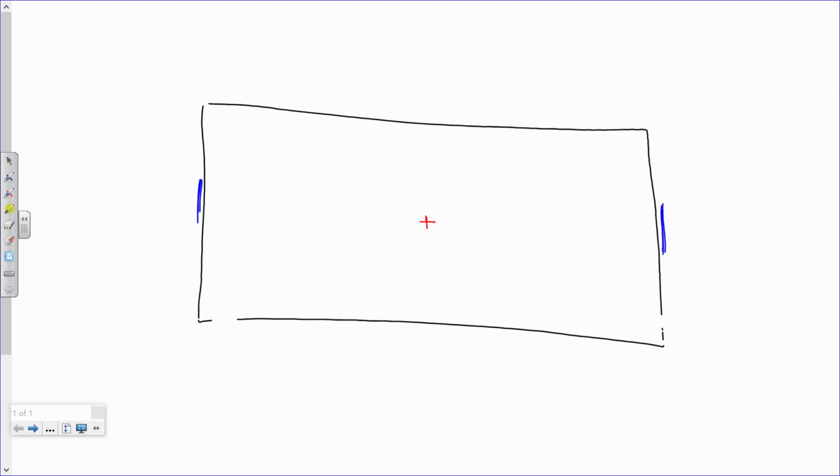If I've got frames that are equally sized on either side, I propose that the center of rigidity is also right here, right? But what happens if I have a really strong brace right here and just toothpicks over here? What happens there is I have a little bit of a difference between where my center of mass is and where my center of rigidity is.